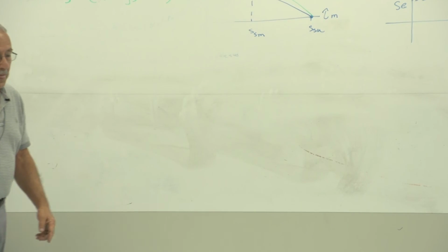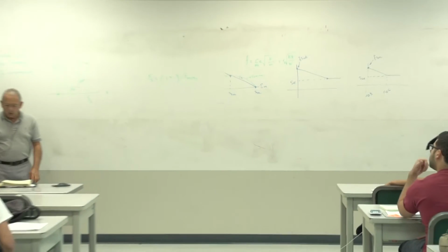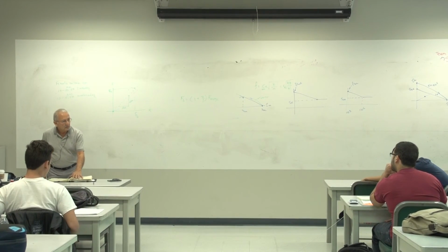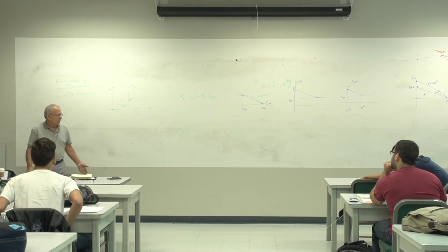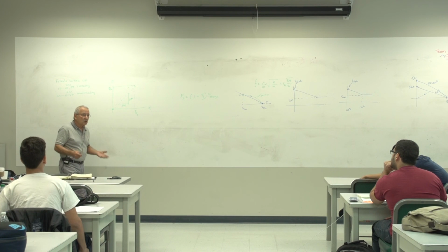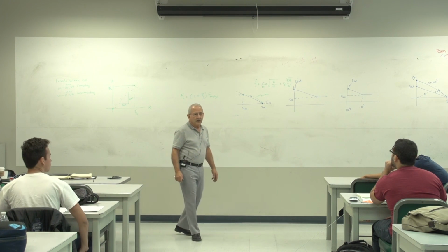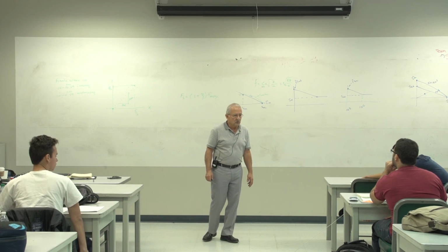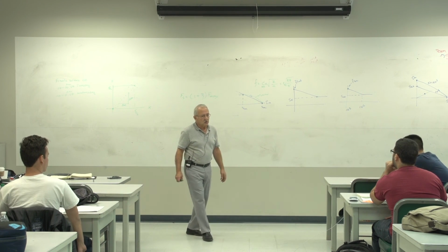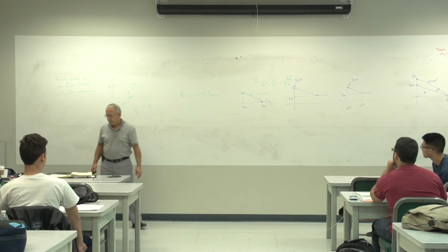Yeah, I guess my question was that if you had a larger factor of safety, would the surge be less important because the spring can handle it? No, they have nothing to do with one another. Although they're both related to the geometry of the spring, other than that, there is no relation between them. You must always check for surge. Okay?